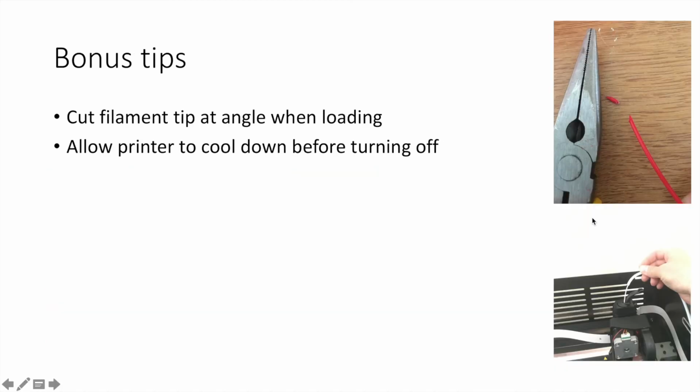I want to leave you with 2 bonus tips that I found to be helpful when using the printer. When loading the filament, try cutting the filament tip at an angle because it helps it feed into the extruder. And lastly, make sure to allow the printer to cool down before turning it off. It has a fan that starts turning on, and if you turn it off before the fan cools it down, then it's going to cool down very, very slowly on its own.